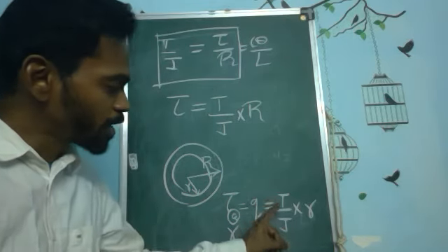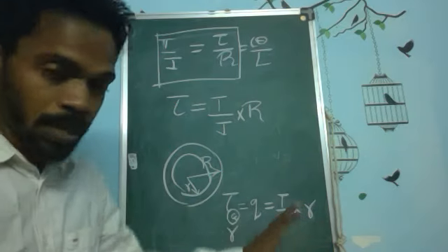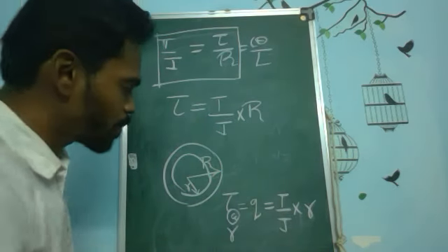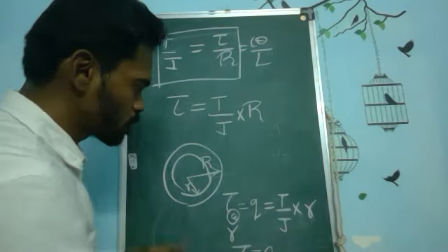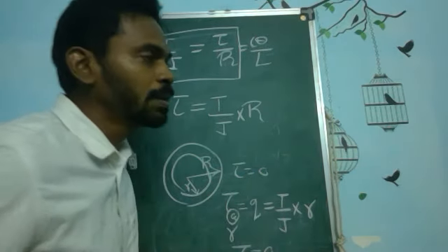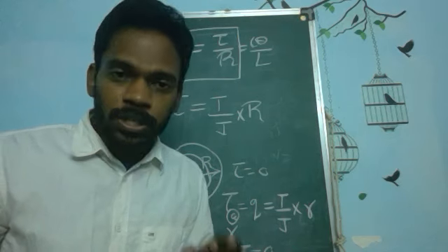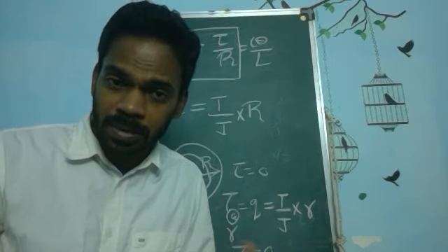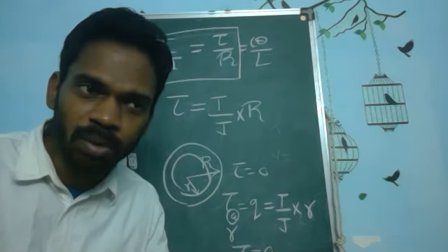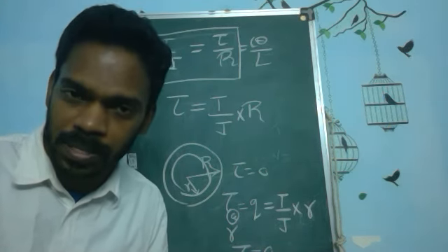If you are trying to define the shear stress at the radius 0, when r is equal to 0, the value of the shear stress becomes 0. That's right. So you don't need material at the center because you don't need material to resist at the center, because there is not going to be any stress generated at the center.